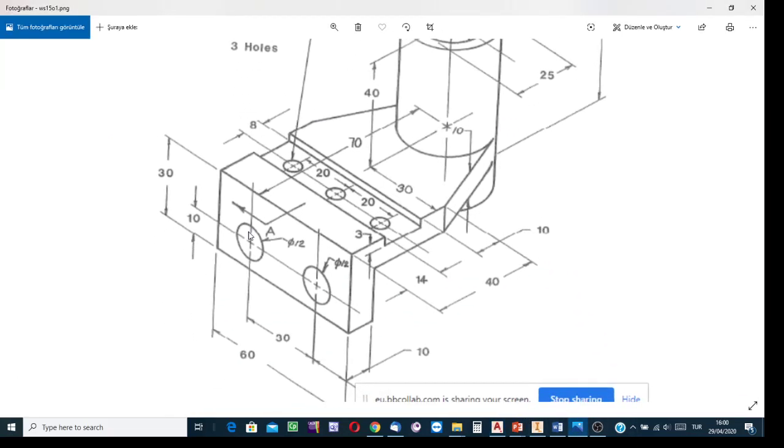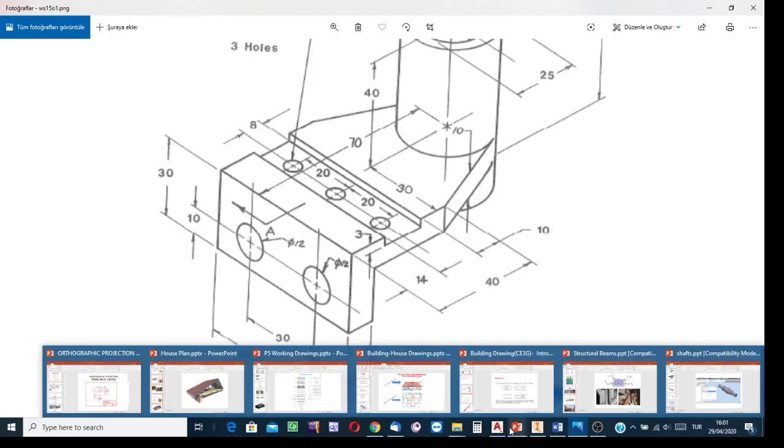For creating the other holes, this and that, I'm going to use the same technique. I'm going to create the edge of one of them, then apply extrusion and then apply the array copy process. The location dimension for the center of this circle, or this one, is 10 millimeters with respect to this edge. Well, 60 minus 30 divided by 2, 15 millimeters with respect to this edge. So 10 and 15.